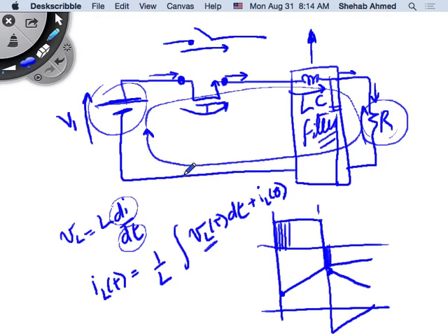In the video, the voltage across the switch became very, very high, so it created an arc. Remember, everything has a breakdown voltage. Air's breakdown voltage is 30 kilovolts per centimeter. This is a 500 kilovolt switch that we saw. You open the 500 kilovolt switch on an inductive load, so the voltage shot up to a lot more than that, and it broke down the air, a dielectric material, because the breakdown of air is 30 kilovolts per centimeter. It broke that down and created an arc.